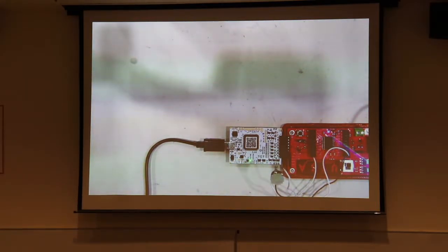And I can have very, very low levels of it. Because, again, even though the LED is completely non-linear, as I give it either full voltage or no voltage for different percentages of my pulse repetition cycle, I can pretty much fully control the brightness and the amount of energy I'm delivering to that LED. So that's why PWM is so nice. And it's also a great way to control a bunch of other things too.